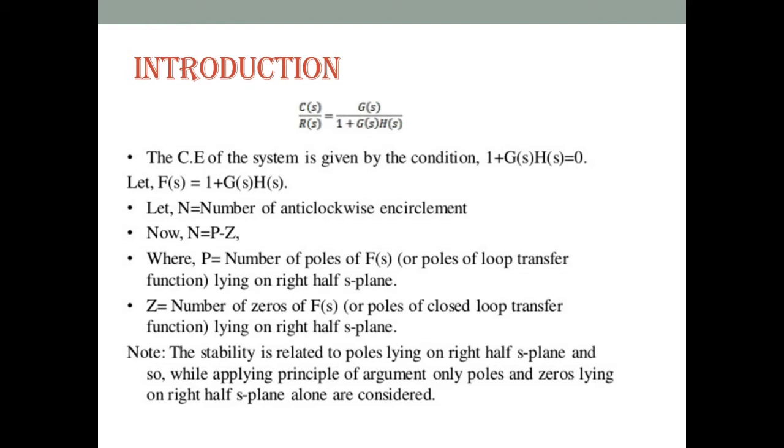Now, the frequency response of a linear time invariant system is dependent on the amplitude and phase of the input test signal. The transfer function of the system can be obtained from the frequency response. The design and parameter adjustment of the closed loop system for specified closed loop performance can be more easily carried out in the frequency domain than the time domain.